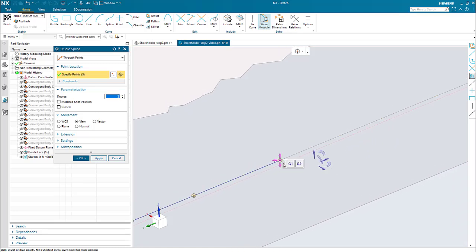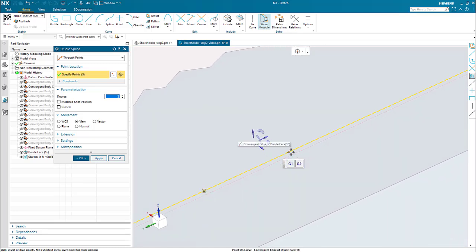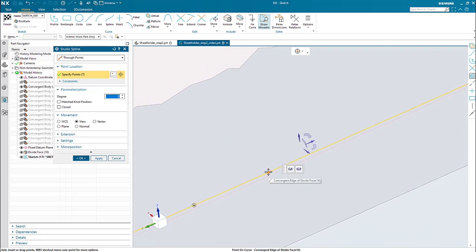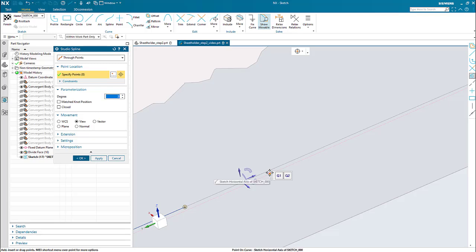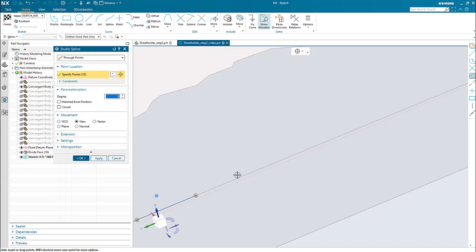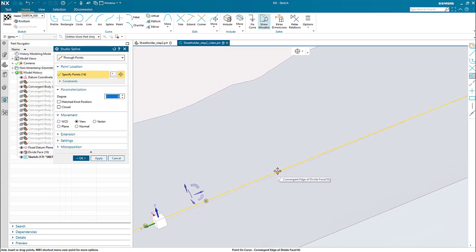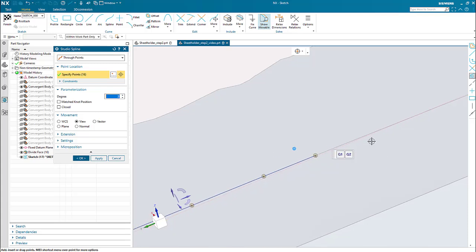Now, we can't choose the curve. We could include this curve in the sketch, but we can't use it directly. We have to recreate it, basically because there's quite a few spline points in this curve on the divide line, so we're just kind of minimizing those. Make sure it's always on this.